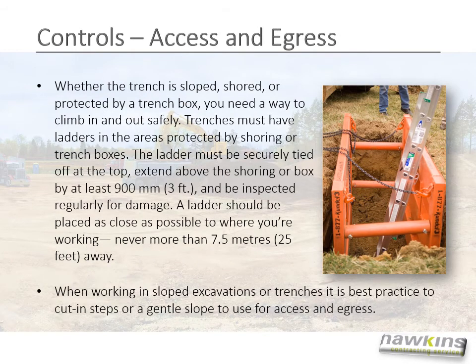A necessary complement to the controls of shoring and trench boxes are ladders. Whether the trench is sloped, shored, or protected by a trench box, you need a way to climb in and out safely. Trenches must have ladders in the areas protected by shoring or trench boxes. The ladder must be securely tied off at the top. It must extend above the shoring or box by at least 900 millimeters or 3 feet, and be inspected regularly for damage. A ladder should be placed as close as possible to where you're working and never more than 7.5 meters or 25 feet away.